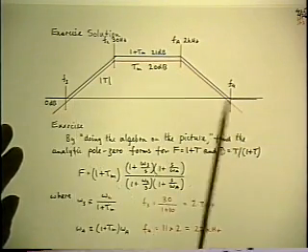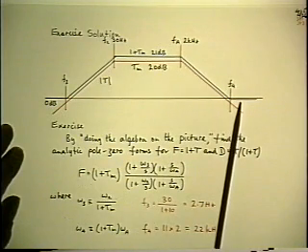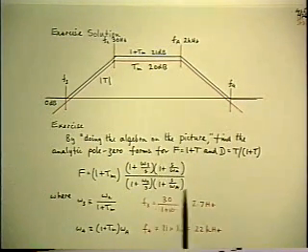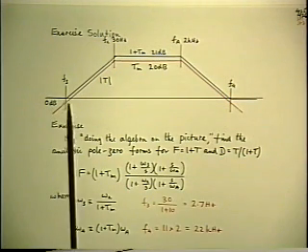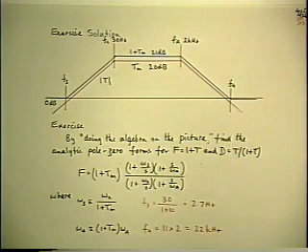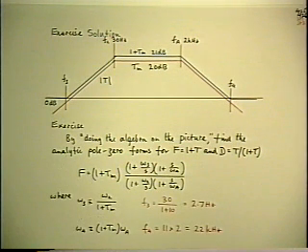We're assuming these two corner frequencies are so far apart that they don't interact. And it was such a good approximation that you don't even notice it. It was so obvious graphically. 2.7 hertz, 22 kilohertz. A long way apart. That's the big ratio that validates the Q factor of the quadratic being so small.